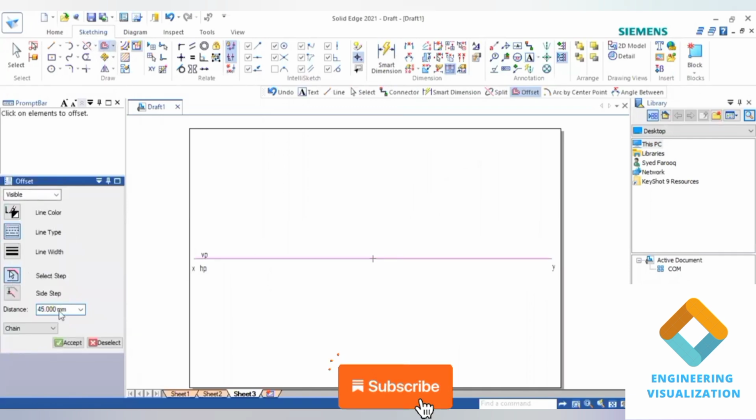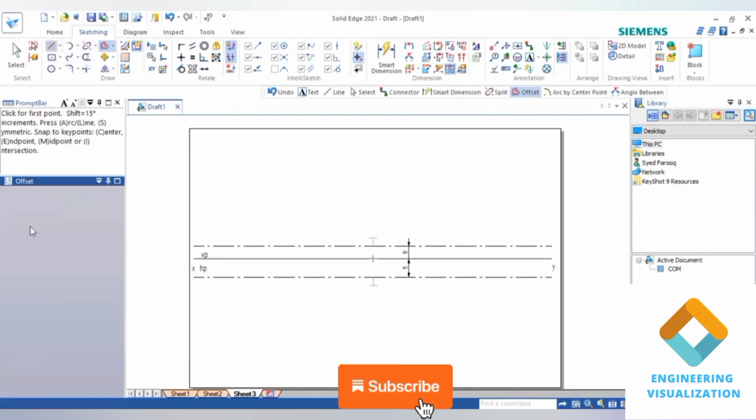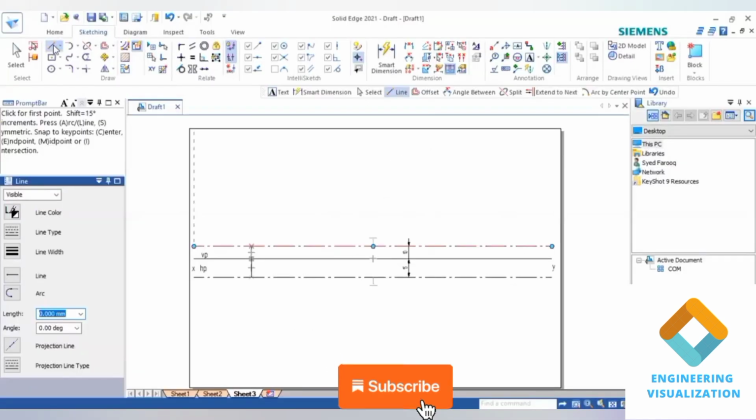Now we have to draw these locus lines. I'll be using offset command. So select the XY line and give the dimension 10 mm. In the same way again you select XY, give the dimension here 15 mm. Okay, now we can see that the apparent length given here. So apparent length, okay, so this we consider as an end point. Using this 75 and 85 mm, we have to draw the